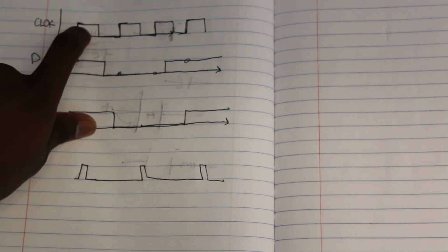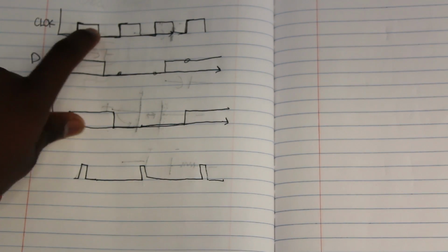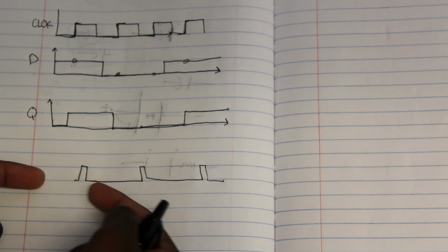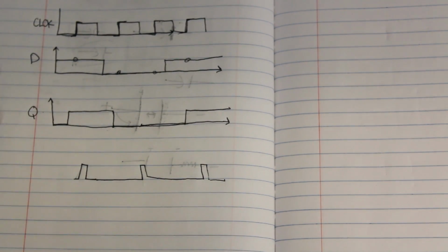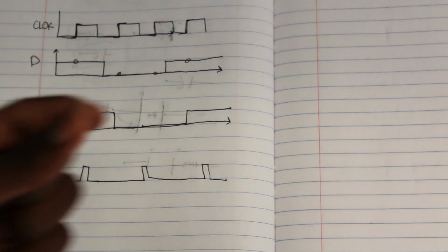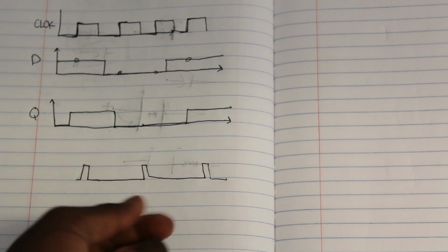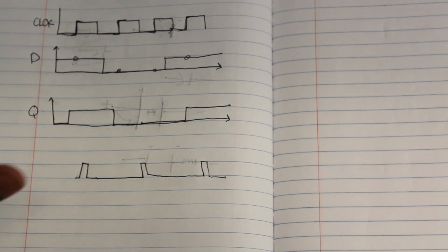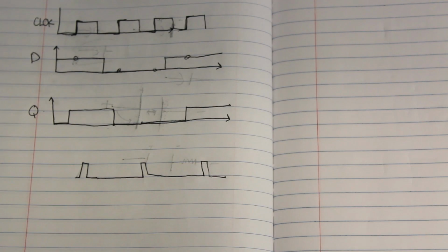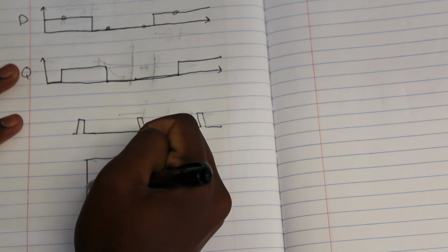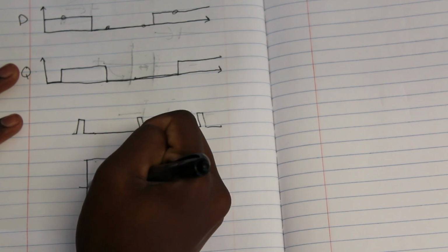And have it be low, and change it really fast again, right? So we don't have to have all this power for this entire time. We can have it really short. We can have it even shorter than this. I'm just drawing it this way so you can actually see it. We can have it so tiny. It only needs to be about 2 or 3 nanoseconds that the power needs to be on for the flip-flop to detect it, and then power can be cut off. No one cares.